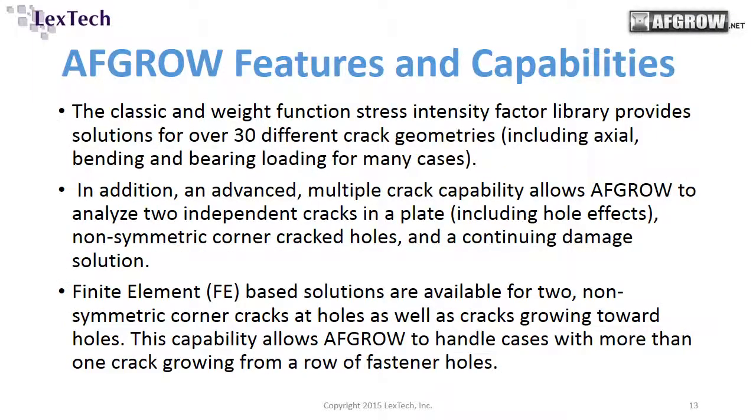Okay, so to summarize the new features, we have the classic wave function solutions for over 30 different crack geometries, in many cases axial, bending and bearing loading. We have advanced multiple crack capability. We can look at 2 independent cracks in a plate, including the hole effects with up to 4 holes. We can do the non-symmetric corner cracked holes, and as I mentioned, the continuing damage solution for a crack that has grown to one edge.